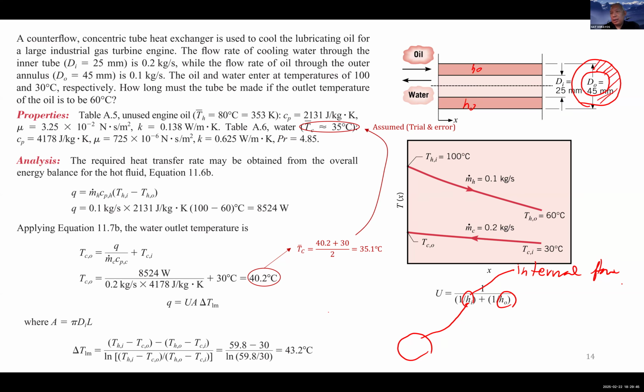This one looks good. It's used for turbulent flow, and you just substitute your Reynolds number and Prandtl number for the fluid inside the tube, which is the cooling water. Once you find the Nusselt number, you recognize that this Nusselt number is equal to HI multiplied by D over k.